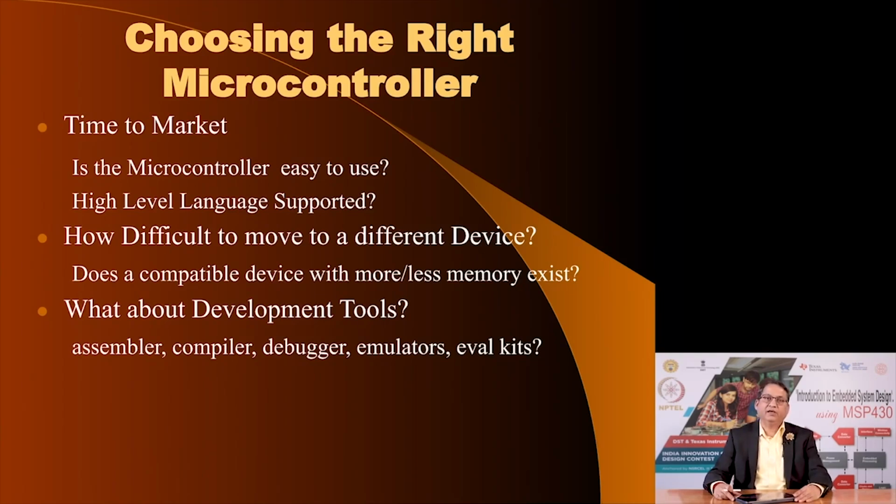have that functionality. In the olden times, you would actually get a specialized device called an in-circuit emulator, which was an expensive piece of equipment, but today almost all modern microcontrollers are equipped with an on-chip emulator, on-chip debugger, which allows you to emulate the function and verify whether the program is working or not, and if it is not working, what is the reason.